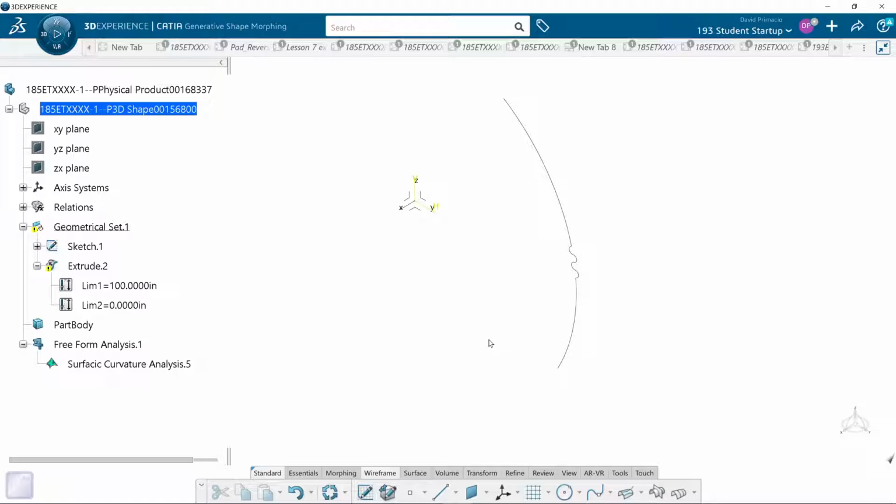Or you could run reflection lines on a surface, and what you would look for is little gaps. So let's say you are shining the light on the wall, but the light hits the table, right? Well, where it hits the wall is not going to be a perfect circle where the light is hitting the table, correct? So the reflection curves that intersect the surface are going to be jagged or offset, and that's how you know, hey, something's weird about this surface right here, because it should be nice, smooth reflection curves on the surface.